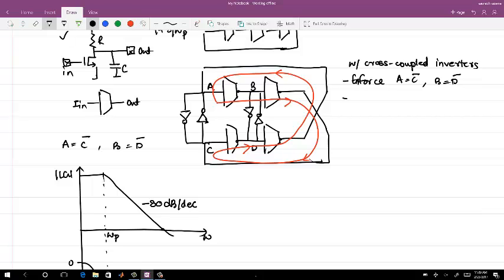Now this 180 phase shift is very direct. How can you say that this is a 180-degree phase shift? Okay, negative GM block, you have to look between 2 points. You look at a differential then. Do not look at single ended.